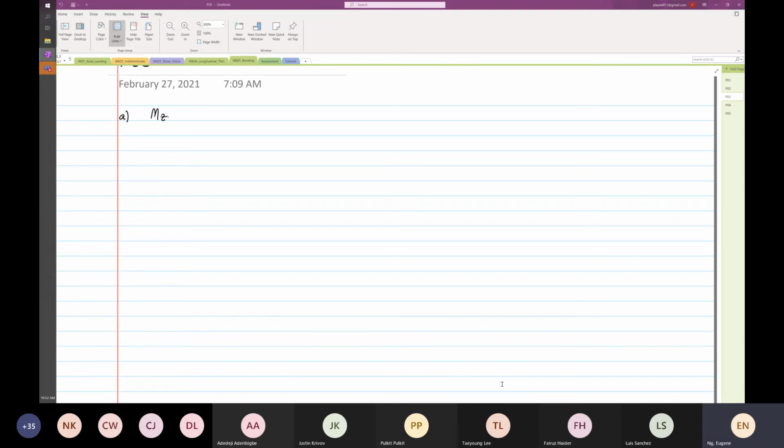Given the moment about the z-axis, we applied the formula where stress x is equal to Mz over Izz multiplied by y. So we found two points.